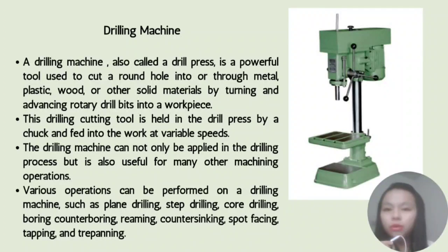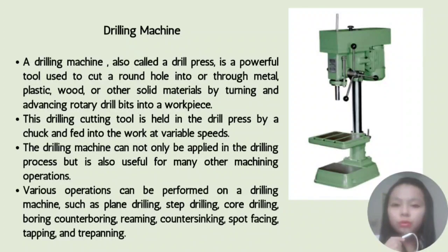Drilling machine, also called a drill press, is a powerful tool used to cut a round hole into or through metal, plastic, wood, or other solid material by turning an advanced rotary drill bit into a workpiece. This drilling cutting tool is held in the drill press by a chuck and fed into the work at variable speed. The drilling machine can not only be applied in the drilling process, but it is also useful for many other machining operations.